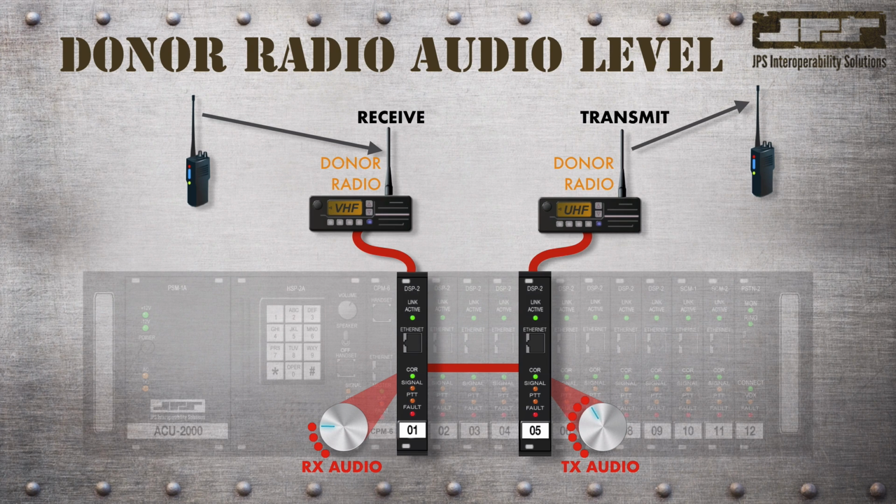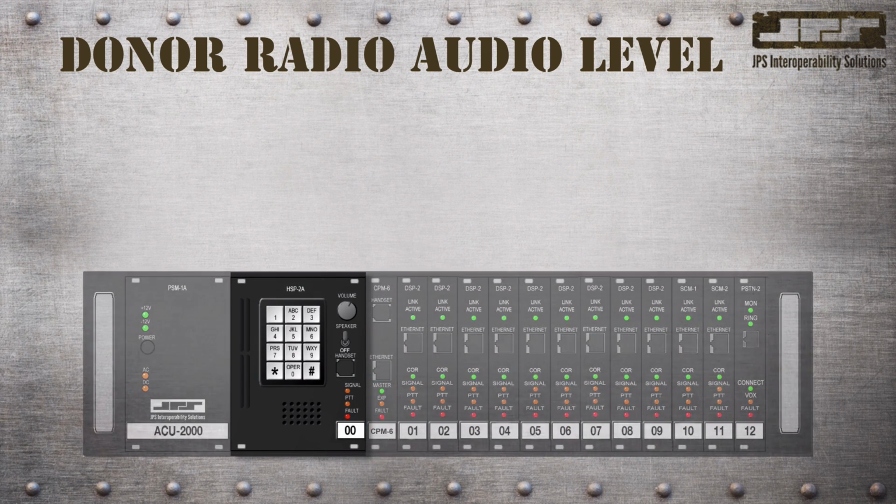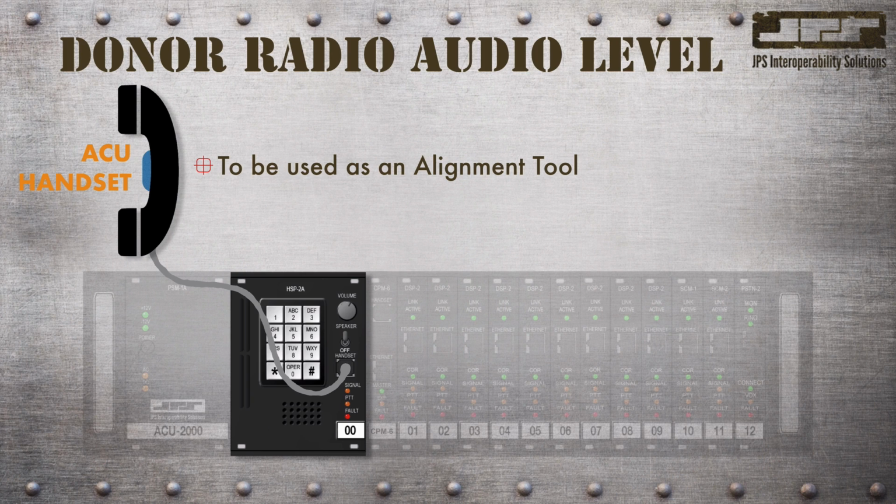Since interoperable voice communications passes through both receive and transmit audio gain controls within the ACU gateway, any misadjustment of one will affect the other. It sometimes becomes difficult to determine which to adjust during setup and troubleshooting activities. We'll use a systematic approach to set both receive and transmit audio levels separately, which will prevent us from making improper and improvised adjustments during actual operations.